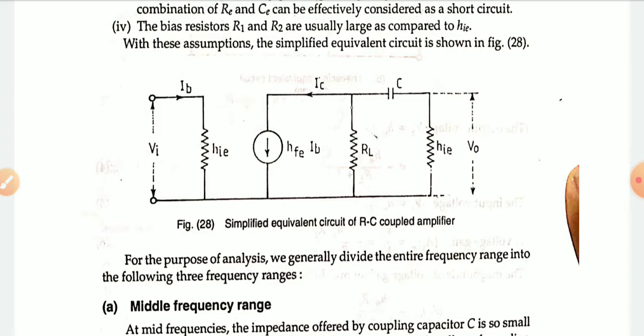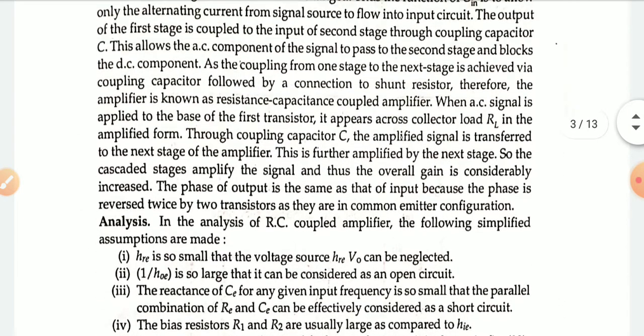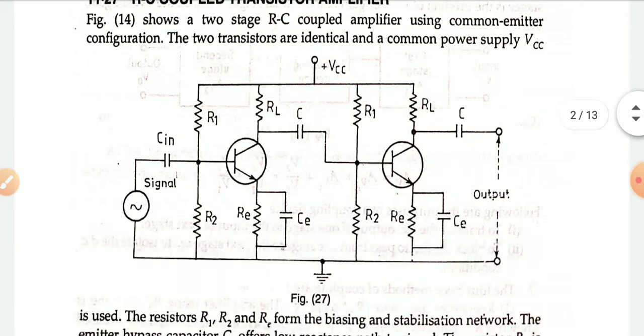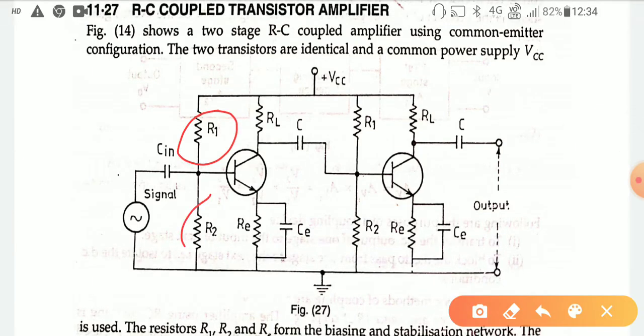First, R1 and R2 for stage 1 or 2 have to be chosen in such a way that in the equivalent circuit the parallel form of R1 and R2 will be a so high impedance, that it works just like an open circuit.